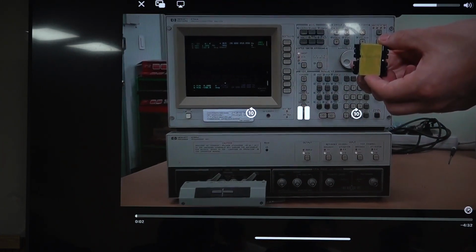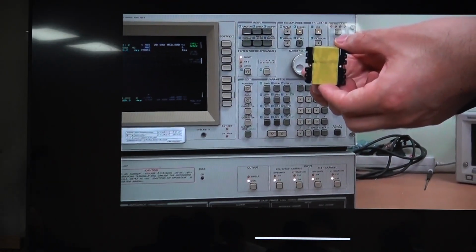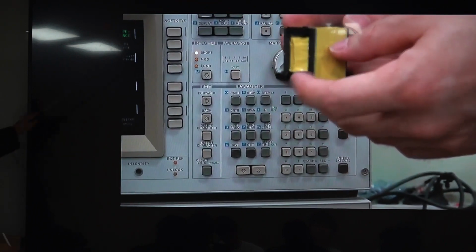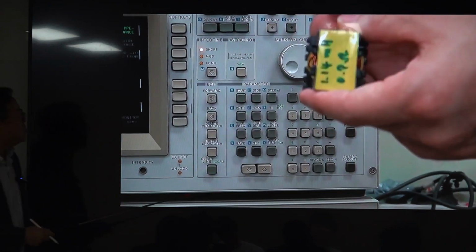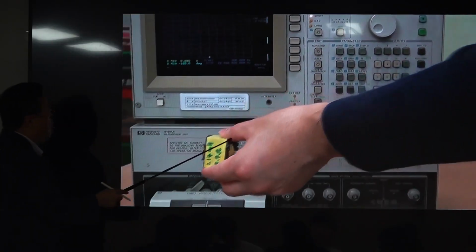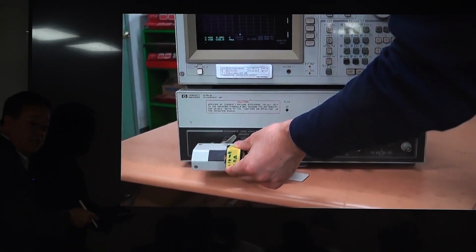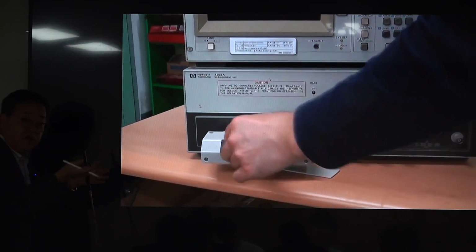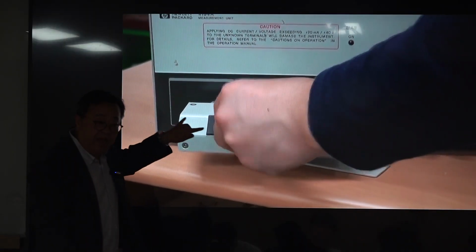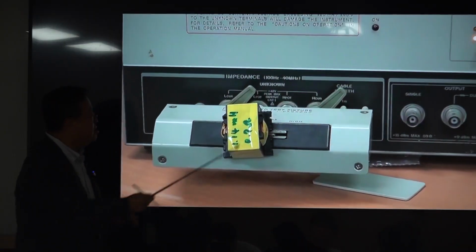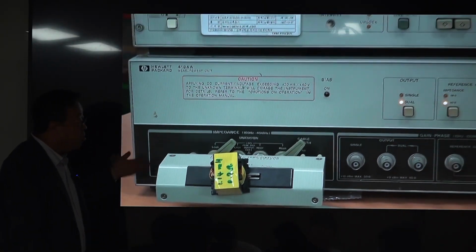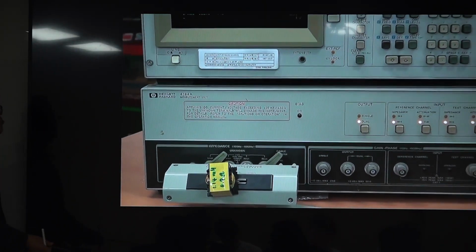This is the impedance analyzer, the HP 4194A. This is the classical one. This is the inductor. Inductance is this one, and this is the resistance of the winding. And this is a jig, the one I explained. It basically contains a good contact clip and a 1 ohm resistor. This cost $1,000 at that time, maybe several $100. And I'm measuring this.